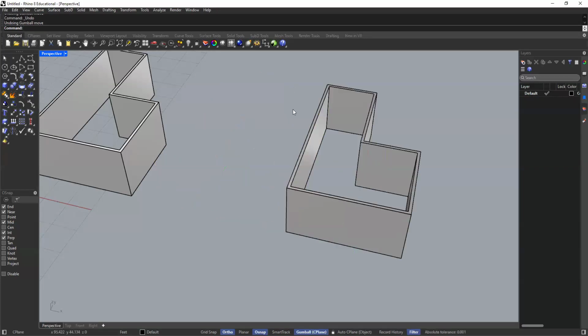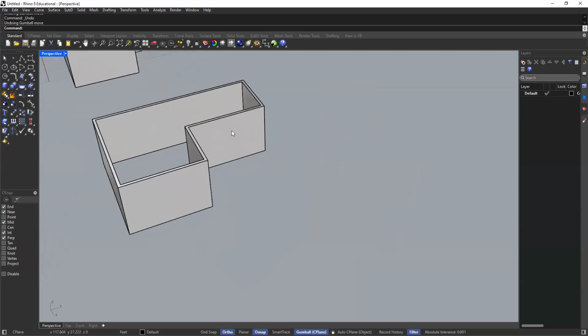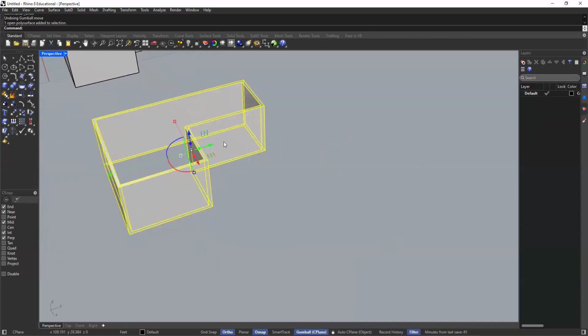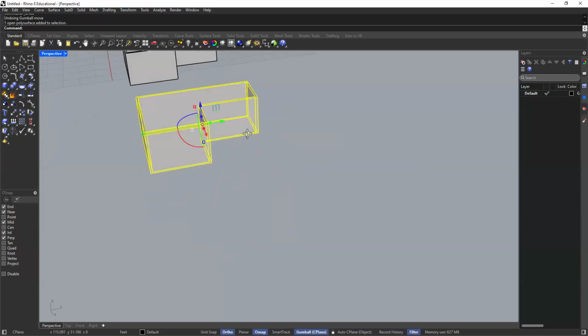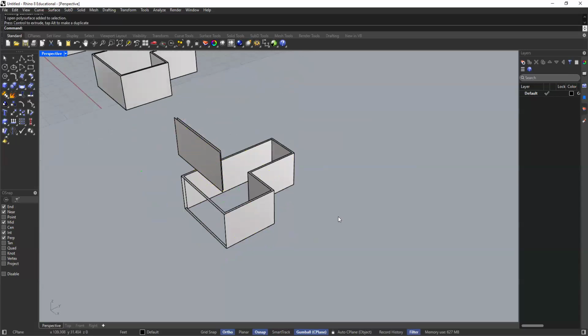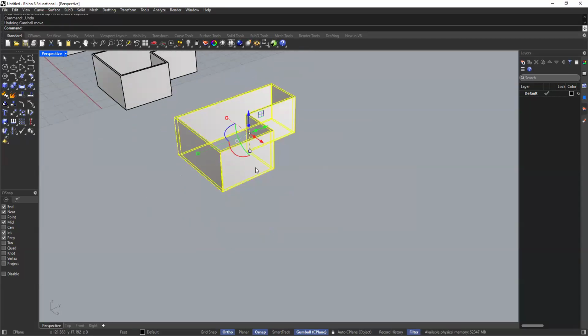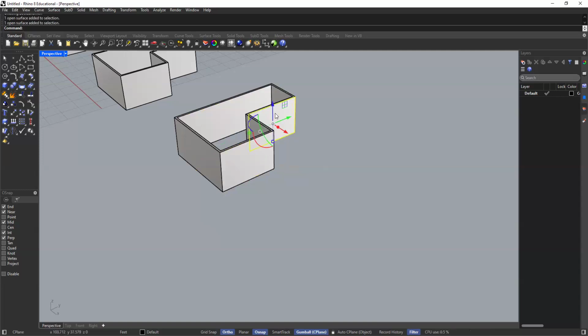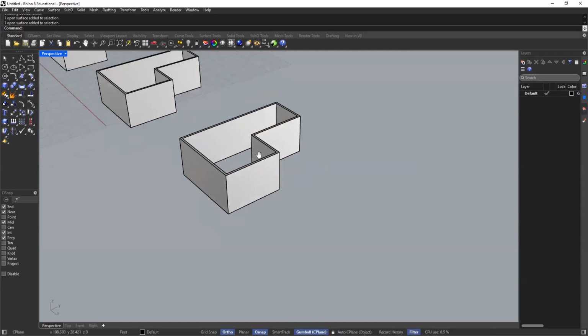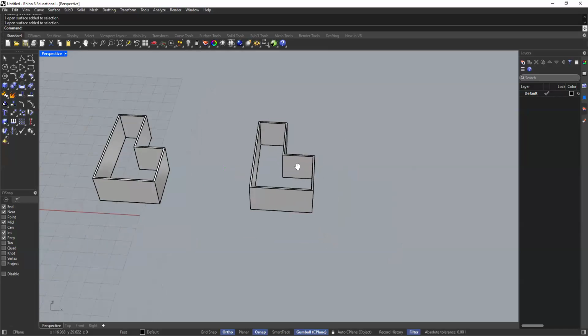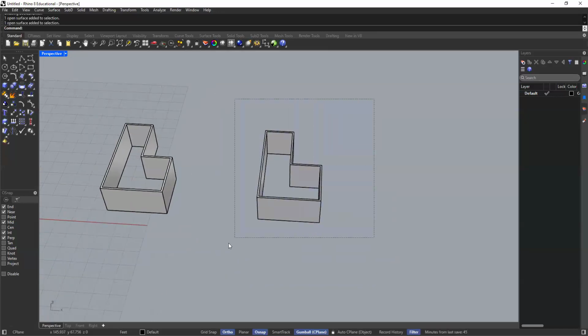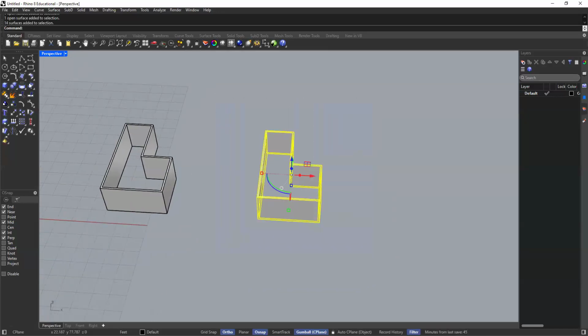And if you don't actually select everything, you're going to click and be like, well, Javier, it's a polysurface. Look at that. It looks perfectly fine. When in fact, it's not. So I'm going to undo back to where it's in the individual surface. The point of this is to make sure you select the entire object. And then come over here and click Boolean Union.